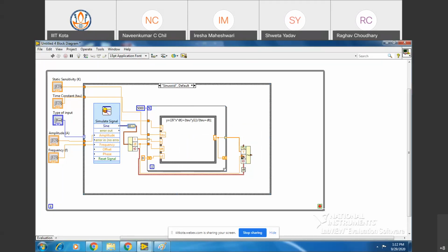Then connect dt of build waveform to the dt of get waveform components. From outside you can take, from inside also, but there is no need. If we just connect the dots, it will wire itself. It wires automatically. Then you connect the t naught also of get waveform components and build waveform. It will synchronize, that timing information is there for synchronization.